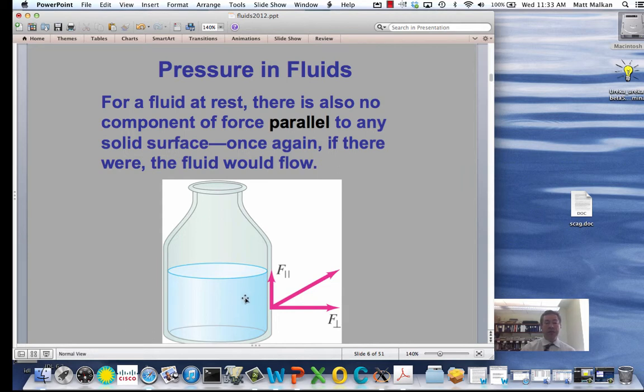So we always know that the force between a fluid and any boundary surface that's in contact with it is always going to be exactly 90 degrees, exactly normal to the surface where the interface is, like the surface of the container. So that's actually a simplification. It's good to keep that in mind. So forget the parallel component. All of the force, which of course translates to a pressure if you just divide it by a unit area, all of the force or all of the pressure is exactly perpendicular to the boundary that you're looking at where the force is acting across.